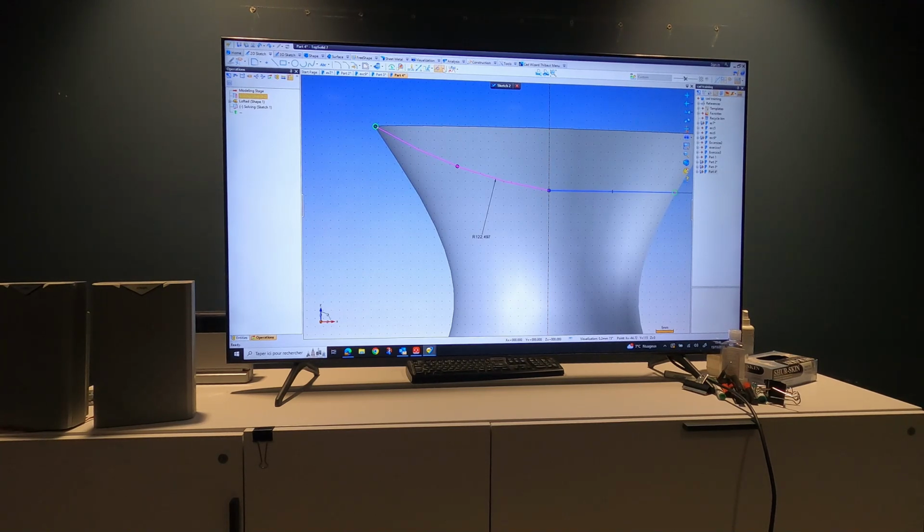Yeah, and you have to say that this bottom point is fixed. It's tangent with this line, and then click on the end. That just fixes that point. And see, now it's blue. I'm surprised the radius and the tangency wasn't necessary. Now you see it's tangent. Yeah. It's nice.